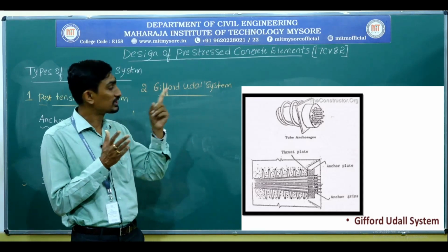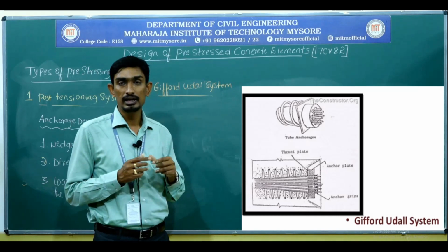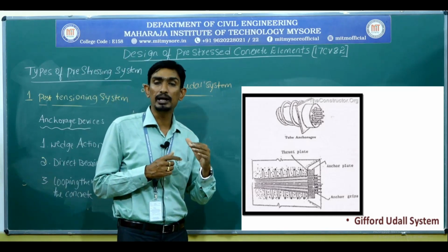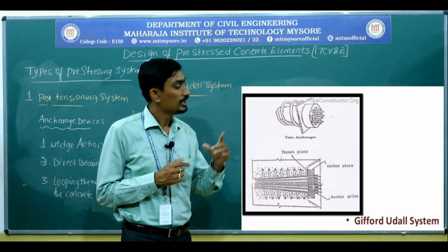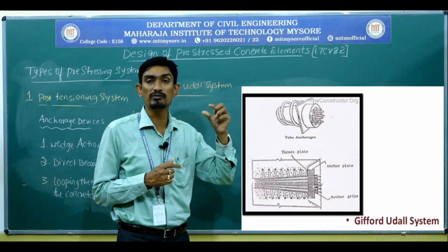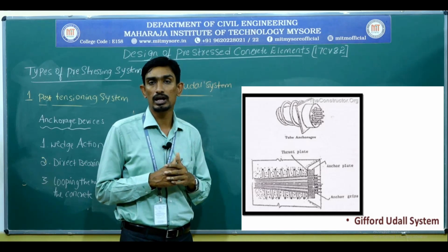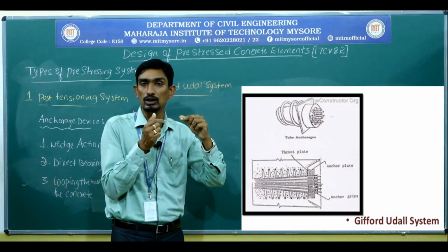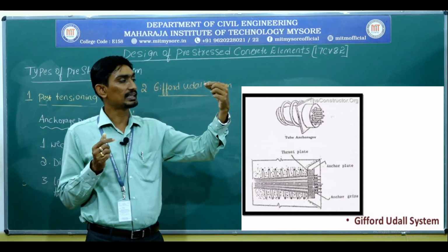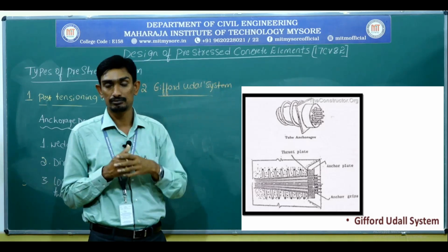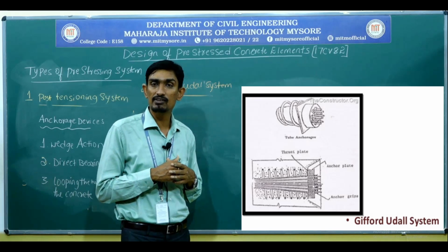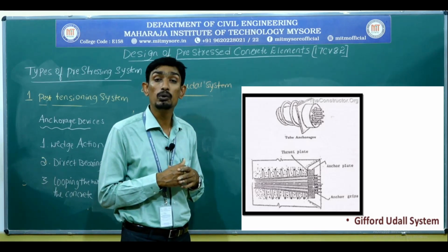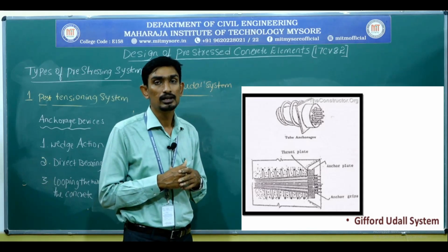It comprises of a steel split core. Through that steel split core, you can see a cylindrical female cone will be inserted. And through that split core and the cylindrical female cone, the high tensile wire will be passed. Now the question will come: how has it been anchored?